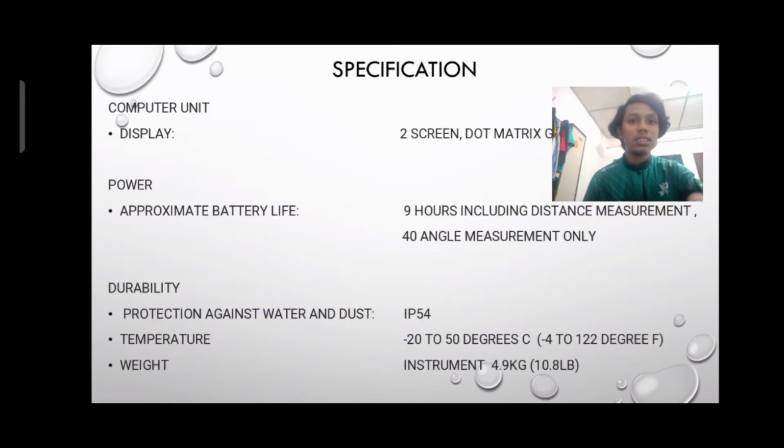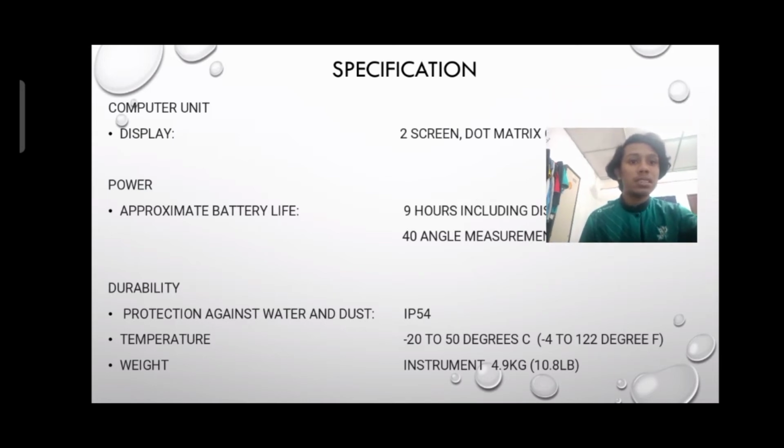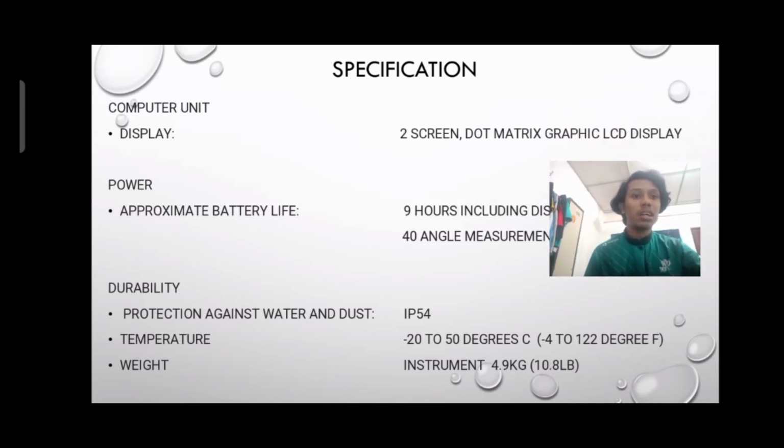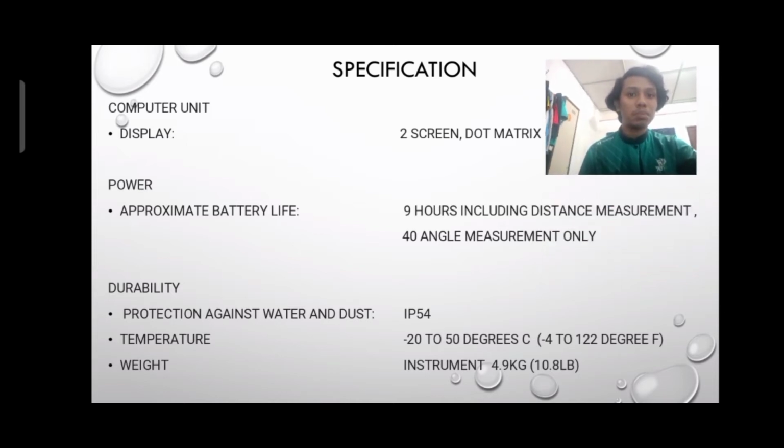Next is about the computer unit. First is the display. The display is a 2 screen dot matrix graphic LCD display that has been used for this total station. Next is power. The approximate battery life is 9 hours including distance measurement, 40 hours for angle measurement only.